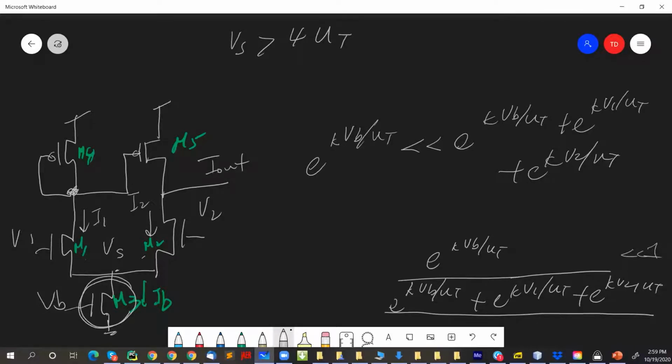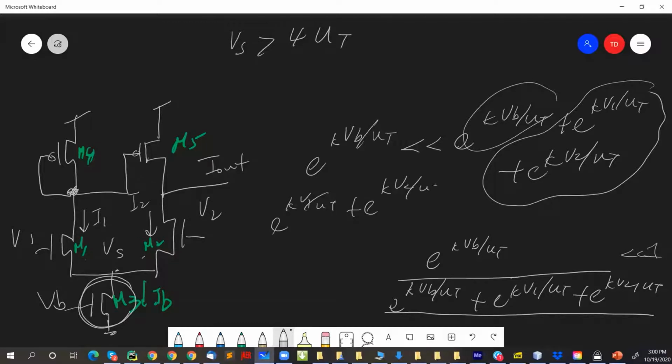Okay, it's good. All right, so that means that now you can redo this. You know that V1 and V2 are both greater than VB. So that means you can assume that these two terms are going to dominate this term. So then you can rewrite this again and say E kappa V1 over UT plus E kappa V2 over UT. So that's where you get equation 2. Is everybody okay with that?